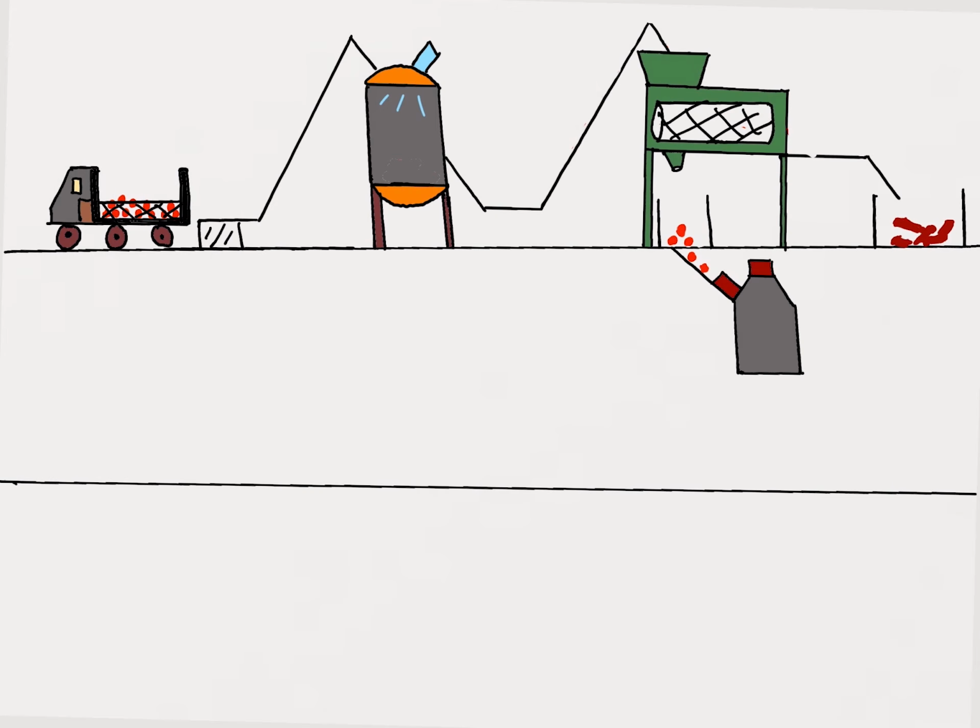The next process is digestion, which reheats the sterilized fruits to loosen the pericarp from the nuts in preparation for pressing. The digestion is carried out in a steam-heated vessel that has rotating shafts which have stirring arms to agitate the fruit. Then the screw press, which is basically a perforated cage that has either a single or double screw.